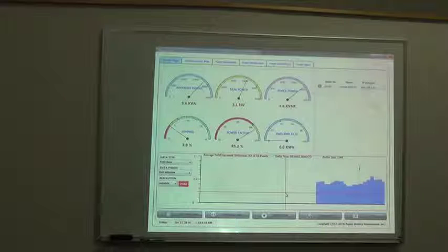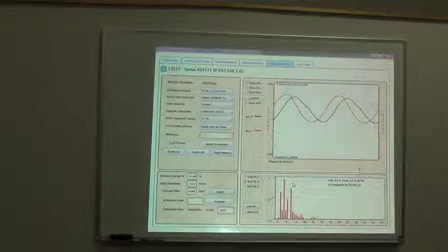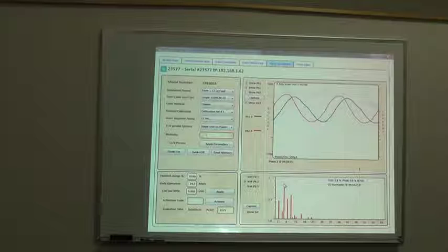The most important thing about harmonics is that we display it. If you go back to this page and you find out that 70% of all of my harmonic comes from one frequency and everything else combined is 30%, then you have a harmonic problem on that frequency. You have to do something about it. You have to go buy a harmonic filter literally for that frequency.